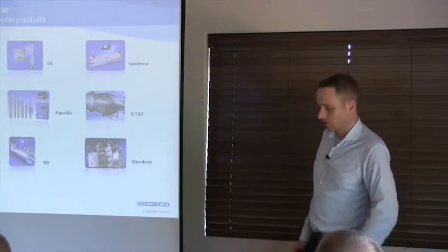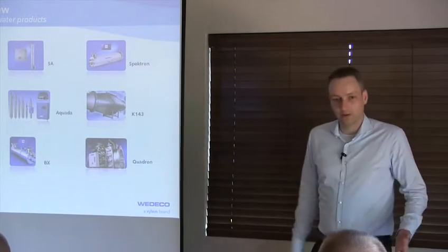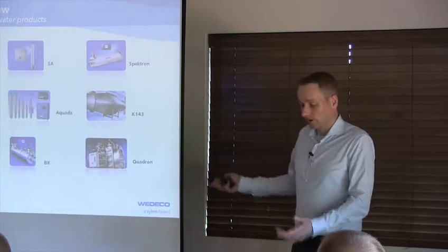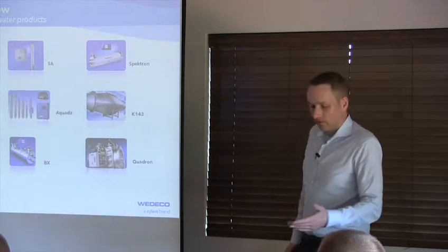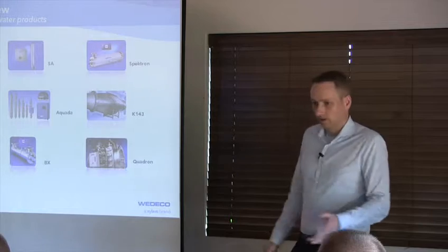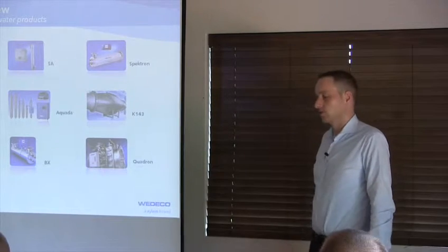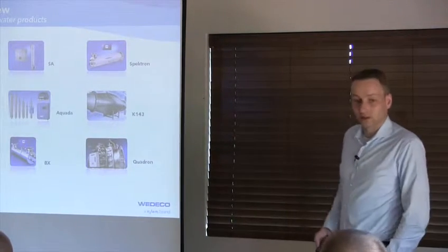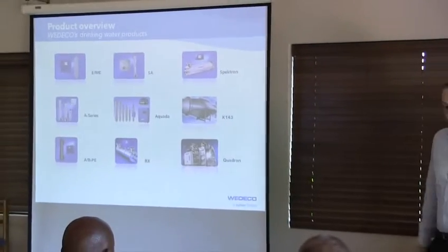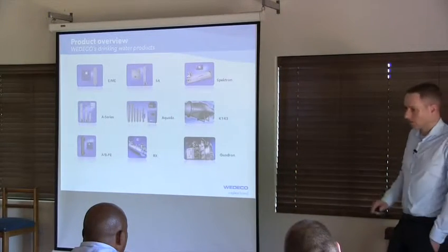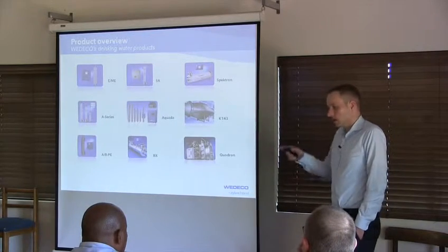If you have good filtration, you can get very high UVTs after tertiary treatment, and the higher the UVT, the better for UV, and the smaller your system. Because of this, a drop of 5% UVT can, in some ranges, double the UV system you need. So UVT is the key parameter, next to suspended solids, for system design. If you're coming to a customer who is interested in UV, the most important question to ask is the UVT: have they measured it, and if yes, how high is it?